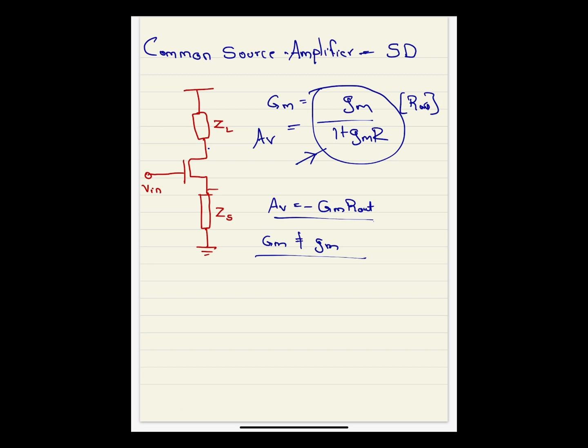You can write the small signal model and use KVL and KCL to get this result, or you can even go with control system theory. One of them is trying to understand how the capital Gm is working and what the small gm is doing, and find a relationship between them, finally getting the desired result.